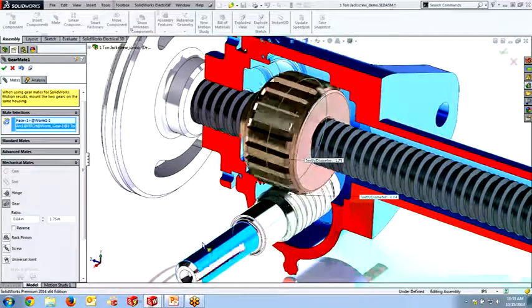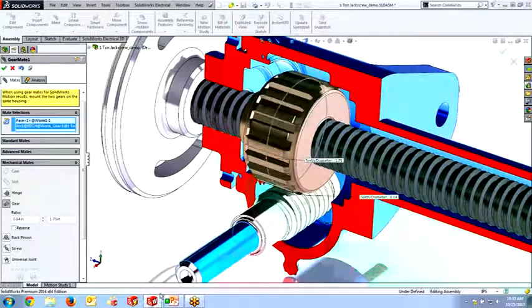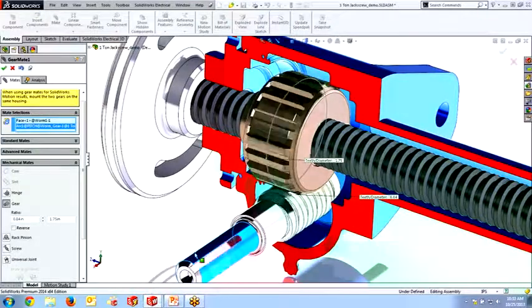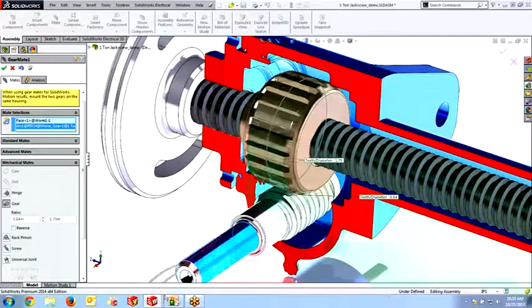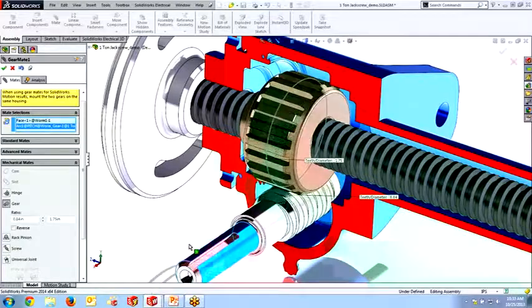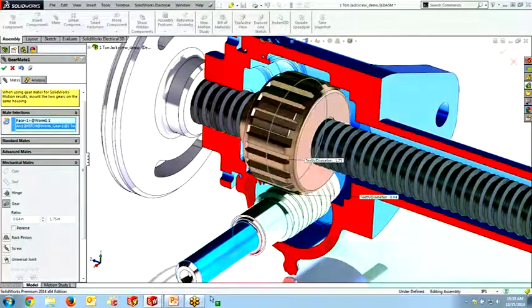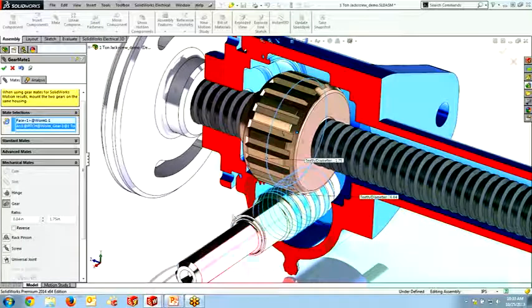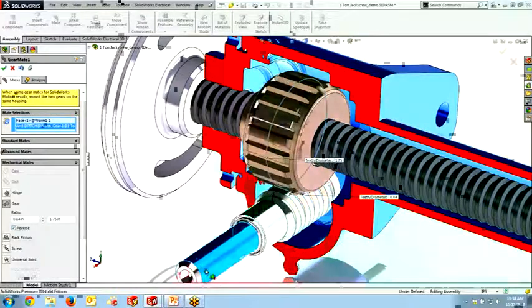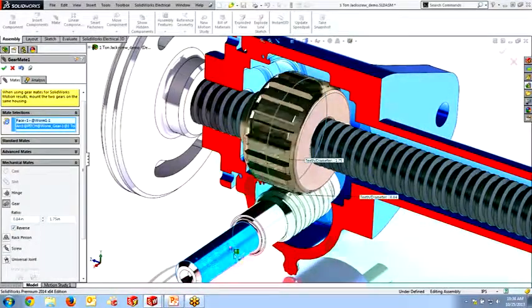Now, I always recommend that people test this out to make sure that the movement is appropriate. And it appears here the movement is not. So as I spin this counterclockwise, or we'll say clockwise, this is moving in the incorrect fashion. Not a big deal. We can always come down here and click on reverse to flip this around so that it's moving in the correct direction.